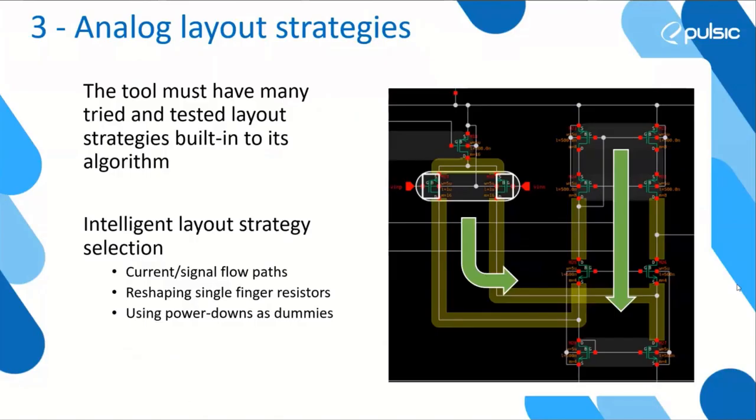Simple things, well, I say simple things, things that analog designers think about are current flow and signal flow through the circuit. They would think about simple things like reshaping resistor fingers and, okay, can I get this down? Using power downs as dummies around devices. All these sorts of things really improve the quality of results, and any tool must take account of those things.